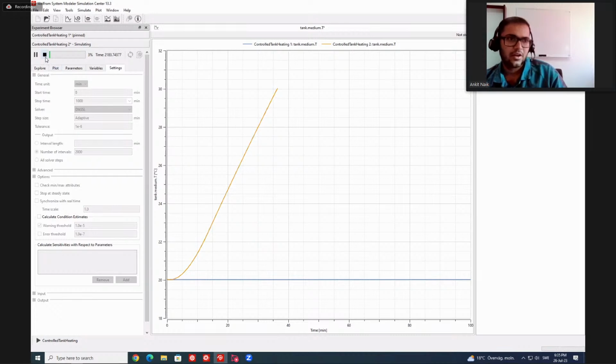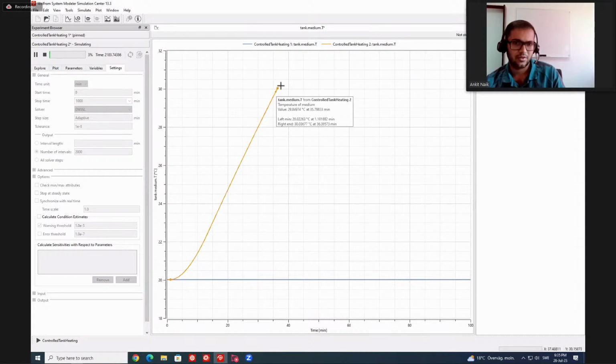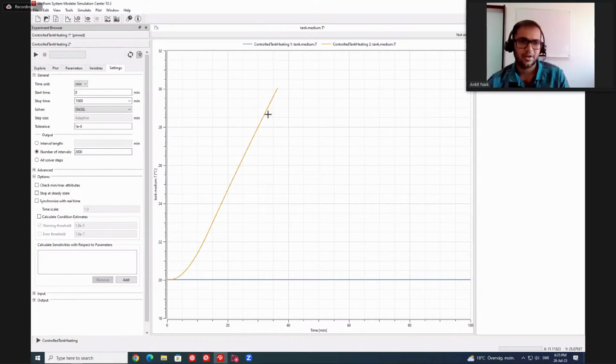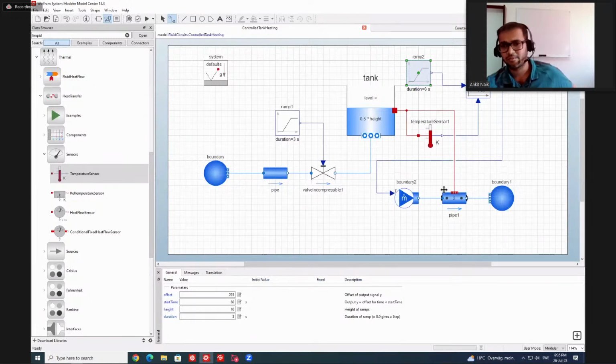Right. Okay. So now again, I think I've reached some kind of ill-conditioned state here, because of which the PID is not able to control it, or I'm reaching some kind of singularity at this position. And then to fix it, I need to tune some of the parameters so that it matches the real world system.